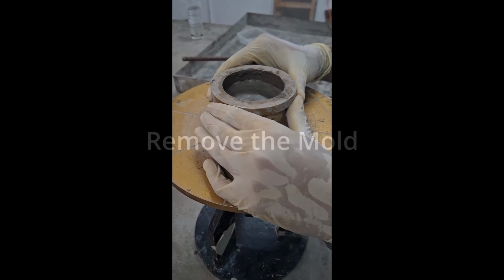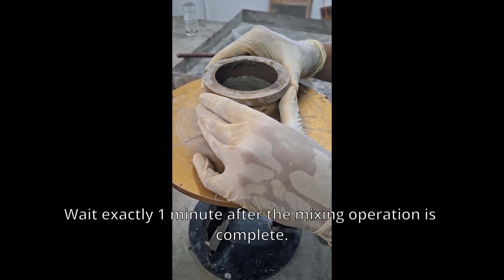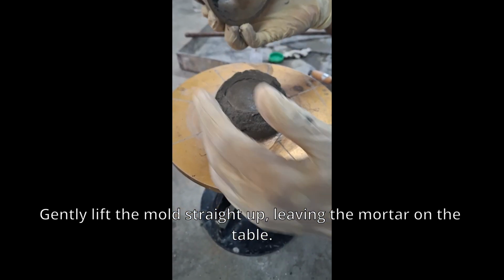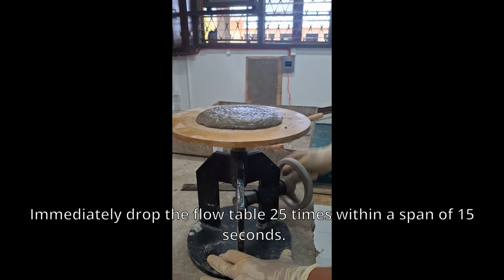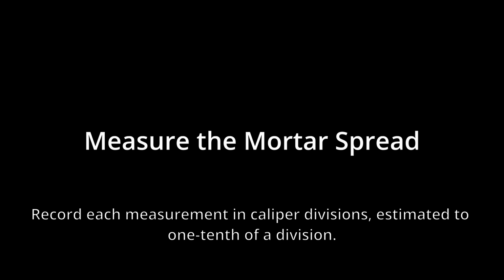Next step is remove the mold. Wait exactly 1 minute after the mixing operation is complete. Gently lift the mold straight up, leaving the mortar on the table. Drop the table. Immediately drop the flow table 25 times within a span of 15 seconds. Last step is measure the mortar spread. Record each measurement in caliper divisions, estimated to 1/10 of a division.